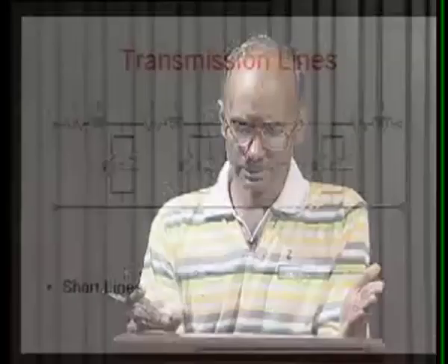In the previous slides, we saw the transformer capability. The transformers are rated to their rated voltage. Again, the voltage is limited by the insulation of the windings, what level of insulation we are going to have, and also what type of cooling you are going to use. So, power rating is decided by the cooling of the system, meaning if your cooling is very strong, very good, then you can go for more loading and so on and so forth.